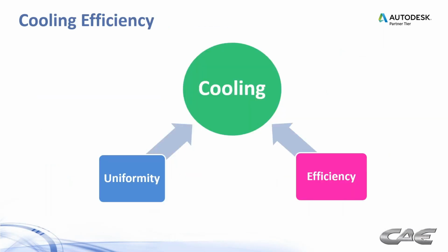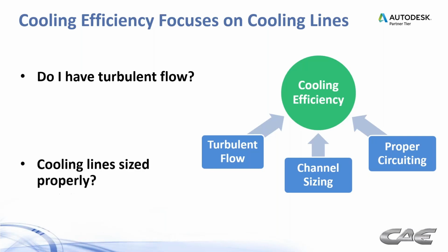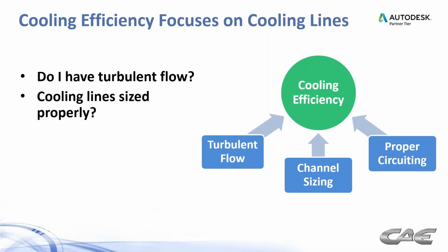So that's cooling uniformity. Now let's talk about cooling efficiency. And now we're going to look at the cooling lines themselves. And there are 3 questions you really need to ask. Do I have turbulent flow? Are the cooling lines sized properly? And do I have proper circuiting?